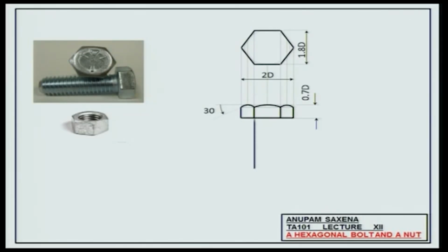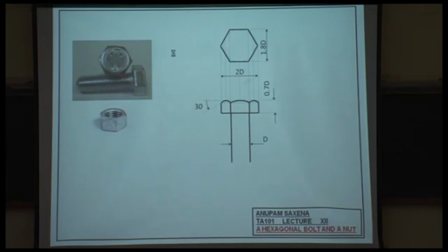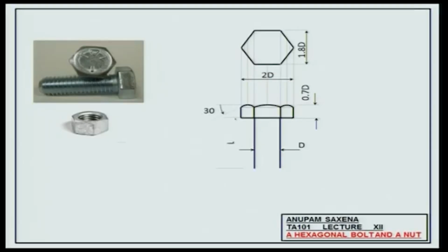Draw the shank of the bolt, diameter D. That measures the outer portion of the threads. You would also be given the length of the bolt and the threaded length, LT. By convention, this angle is 45 degrees. This angle is 45 degrees. There's a little taper down here.